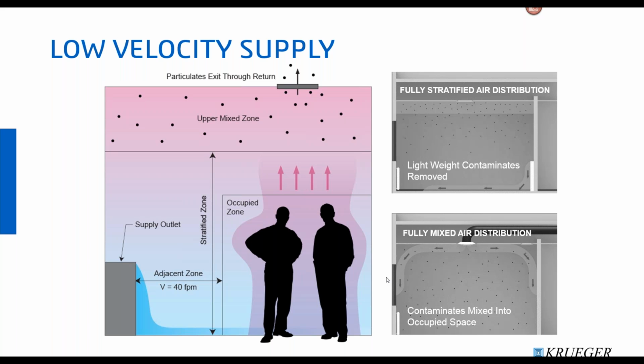In this case, that's occupants or any equipment that might be giving off warm discharge. As that cool air encounters that warm body, it's going to crawl up that entity and exhaust itself upwards towards the ceiling. In this illustration, towards the ceiling, we have what we've called the upper mix zone, and then we have a return grill at the very top of that upper mix zone.